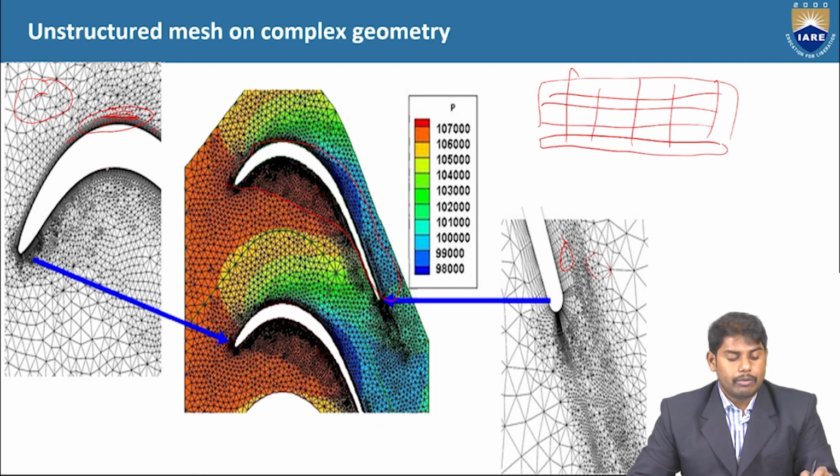This is why we saw initially a coarser mesh and finer mesh, uniform mesh and non-uniform mesh, both along the x-axis and along the y-axis. Here you can see an example where the hybrid mesh, the combination of structured and unstructured, can be used.